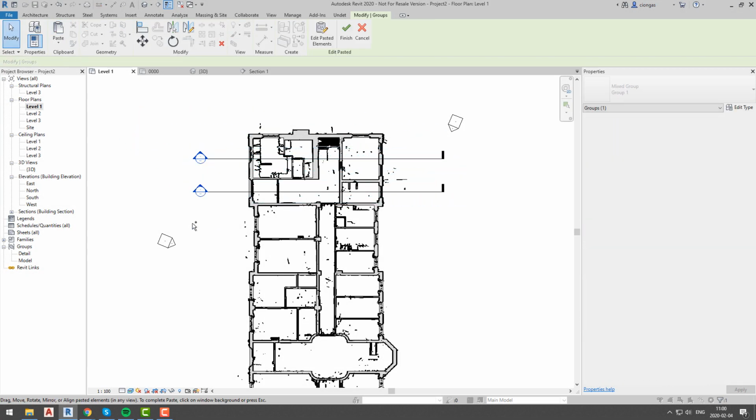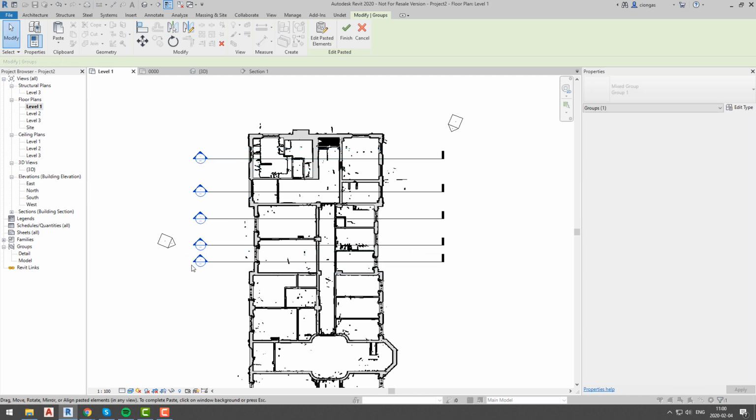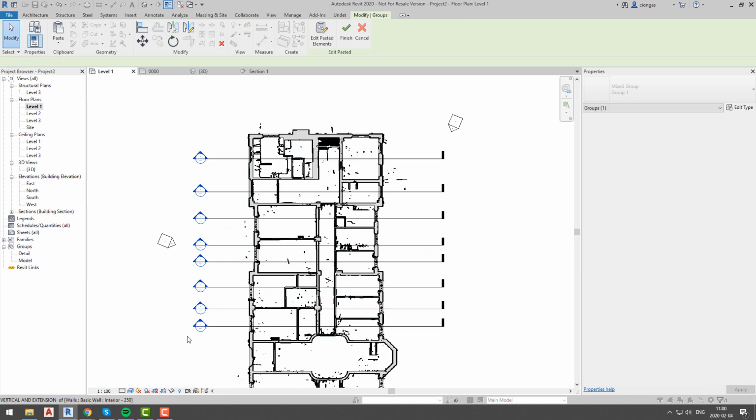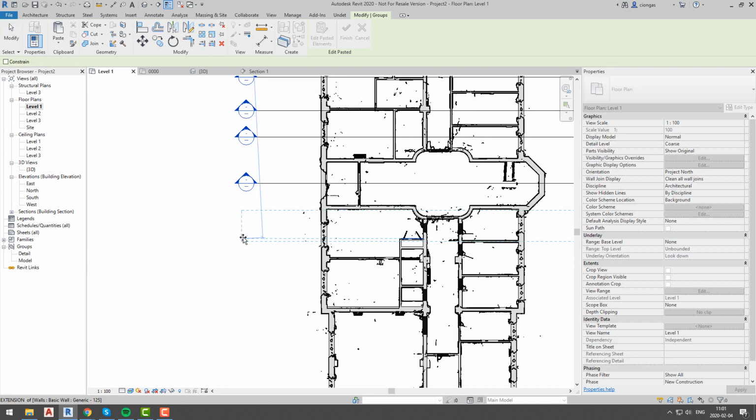Once we have all inside walls, we can add floors and ceilings. We will start from adding horizontal sections throughout every room in our building. This will allow us to adjust ceiling level to correct value according to point cloud information in every room separately.